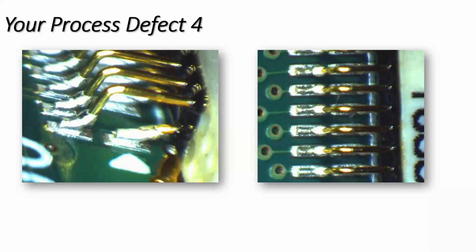So if we say, for argument's sake, you've got air just prior to reflow, the temperature is 240 on the top side heaters. What about the bottom side? Flipping it and make that 260 at the bottom.